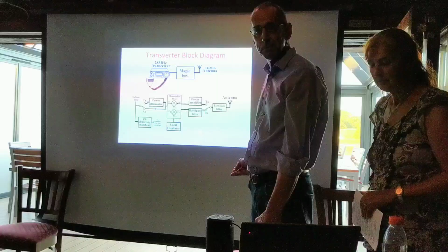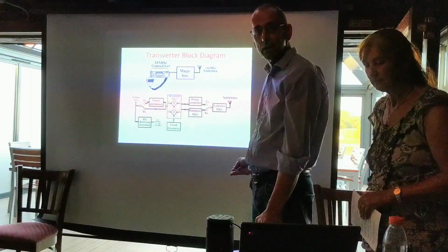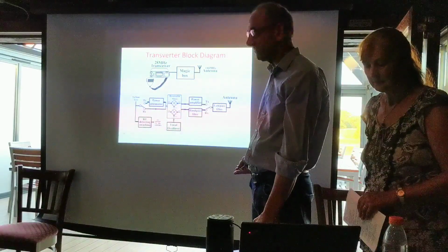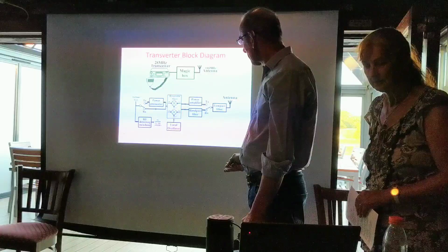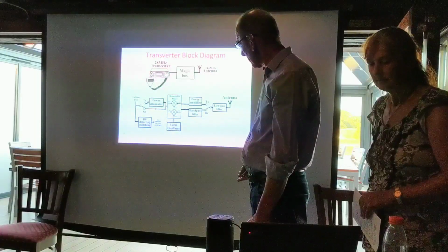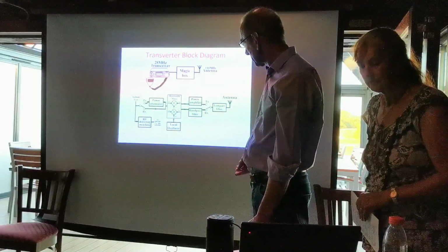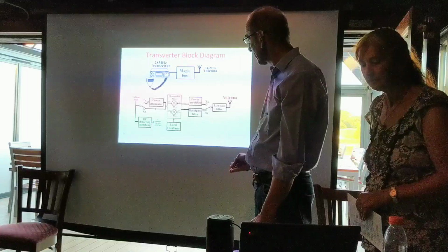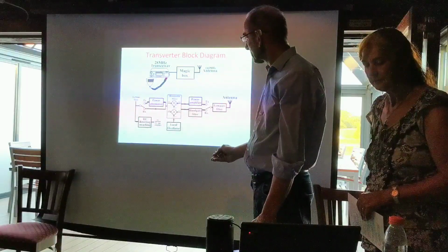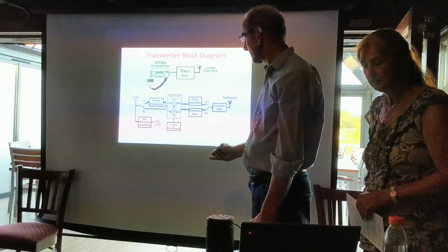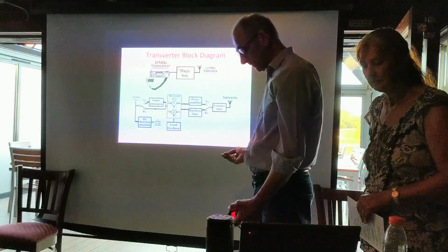The better that is, the better the receiver's going to be, the less weird stuff's going to come out that isn't really there. Now the reversible mixer has to go the other way. The local oscillator, of course, is being used the same for both, and that then feeds the signal into the transmitter that you're using this thing on.